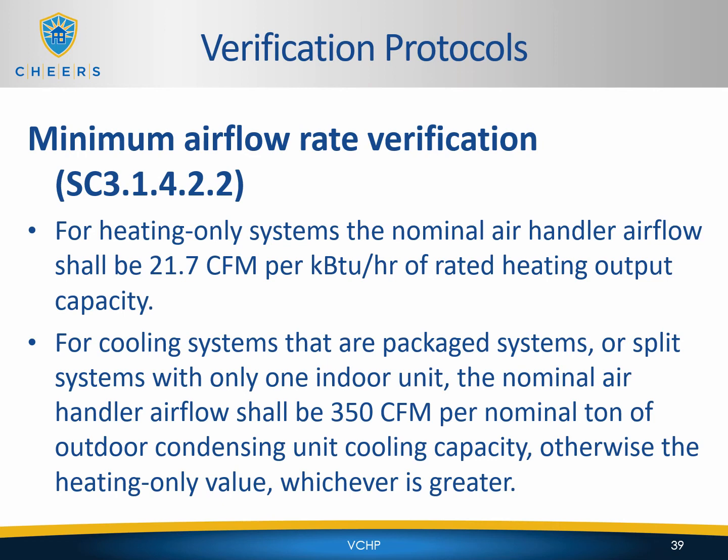And then for cooling systems that are package systems or split systems with only one indoor unit, the nominal air handler airflow shall be 350 CFM per nominal ton of outdoor condensing unit cooling capacity. Otherwise, the heating only value, whichever is greater.